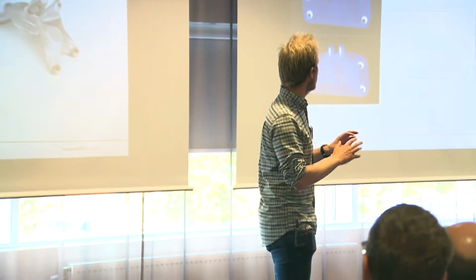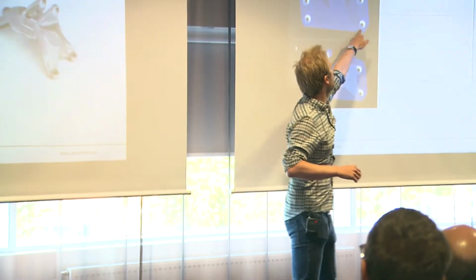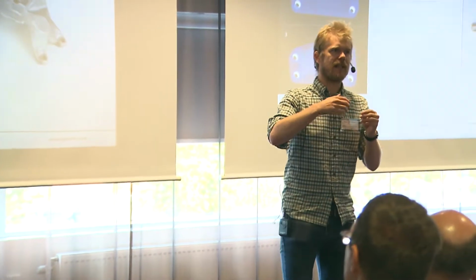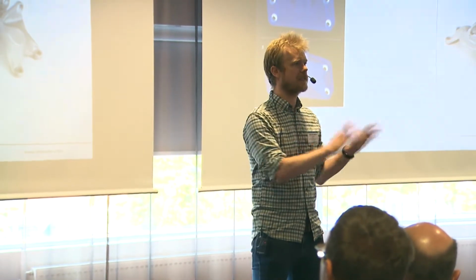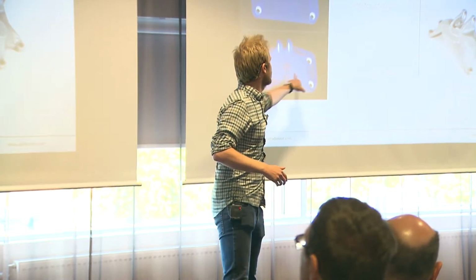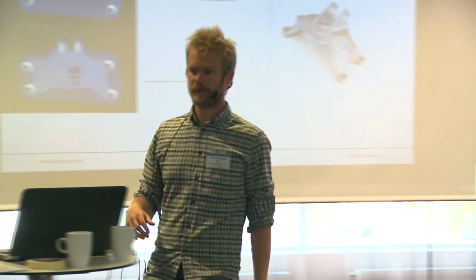Then you define solid volumes. So this is where there has to be material, because I'm going to mount my part. And then topology optimization is an iterative finite element calculation where mass is moved around until it's sitting at the perfect place. So the computer simply spits out an optimized design, fulfilling your design requirements.